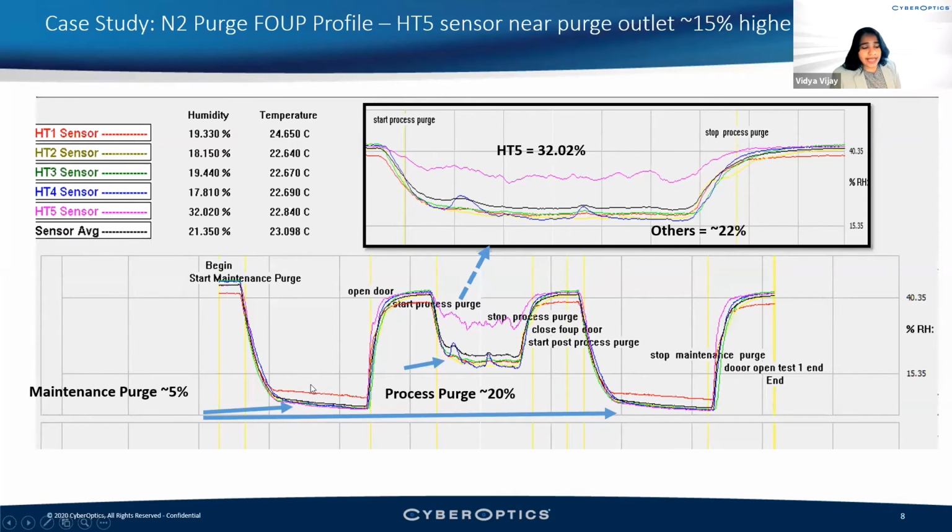And all of this is happening as the graph is plotting, as our AMS sensor is traveling through the tools. You can see one of the sensors is running at a bit higher humidity, and we give the correction curve. That's because it's much closer to the electronics. This is a good case where we can see there is so much change, and each process might have extremely dry cases, and they might require to keep at a certain percentage, and this is helpful to characterize that.